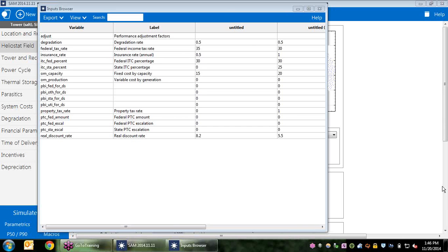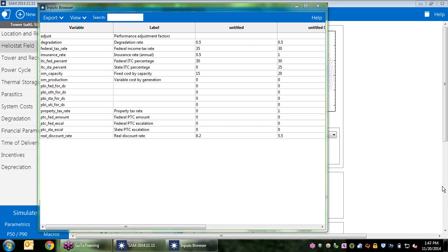And I see another question asking if you can run a simulation using two different types of inverters to sum to a single project. At the moment, the best way to do that in this version of SAM is to create two different cases, and then you will have to post-process the results to sum them. That was a feature that we had in previous versions of SAM, but due to the extensive recoding in this version of SAM, that feature has not been made available in this version yet. However, with the new LK scripting language, it is easier to post-process two cases to add the results together using scripting.